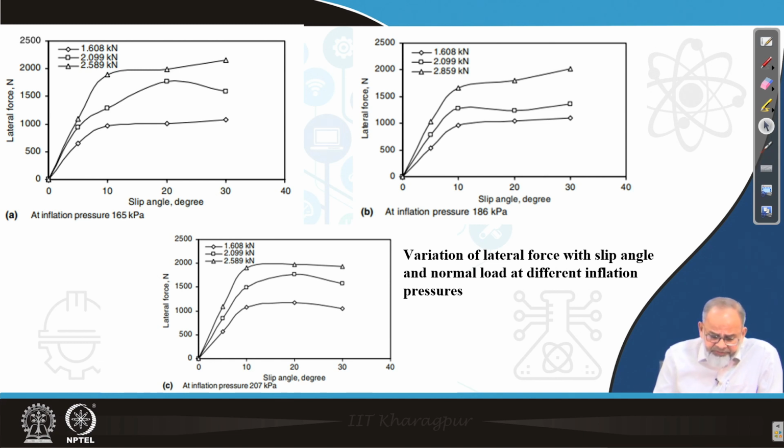The same exercise we tried with 207 kilopascal, and what we observed is the same thing: lateral force is increasing with increase in slip angle up to a certain degree, and beyond that it is either constant or decreasing or increasing.